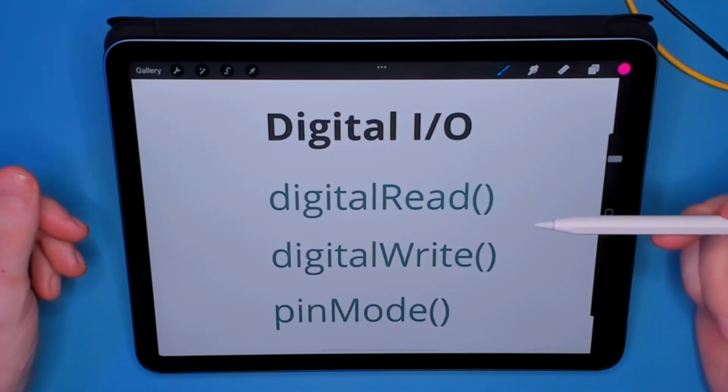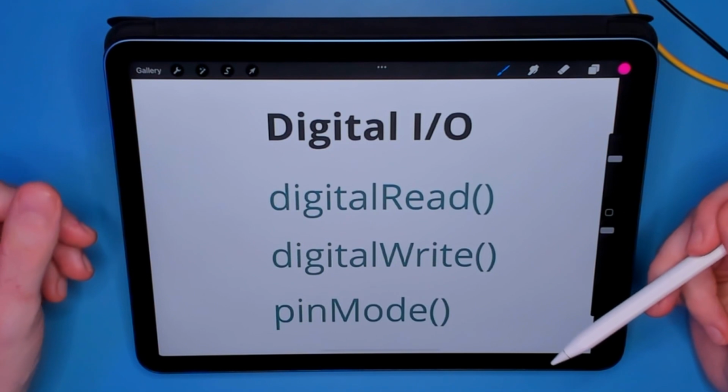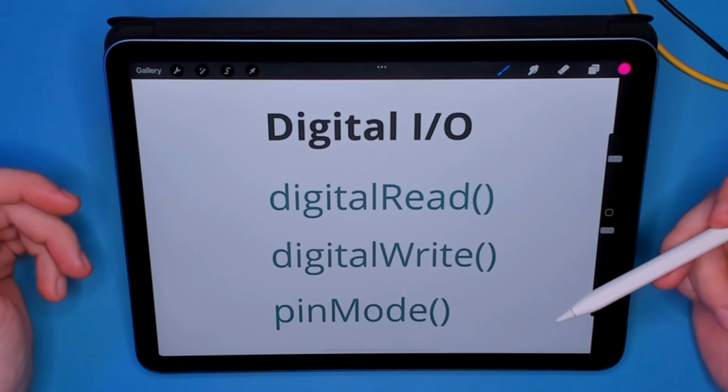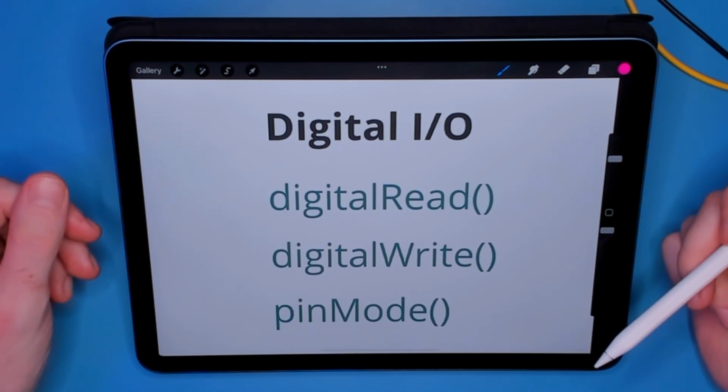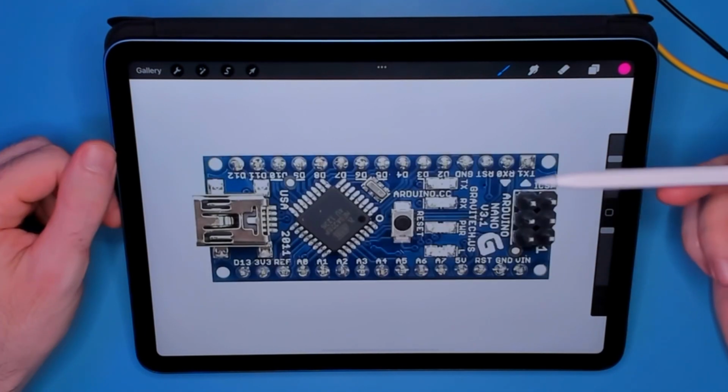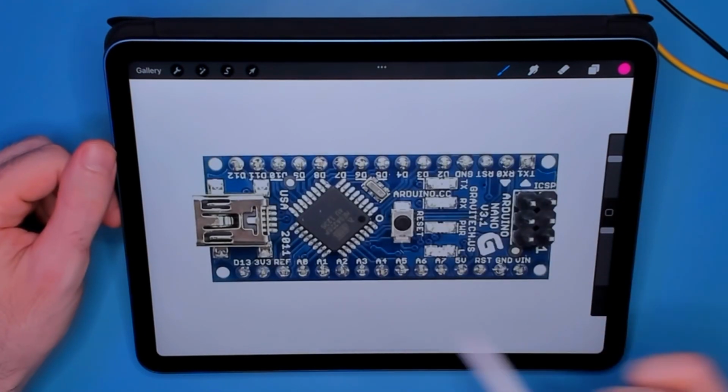Before wiring things up though, we'll need to figure out which microcontroller pins should be hooked up to the DAC. To control the DAC, we're going to need something a bit more advanced than Arduino's digitalWrite. This function, along with digitalRead and pinMode, were lifted from an earlier project called Wiring, and were designed to simplify things by mapping out a set of virtual pin numbers, specifically the ones that you can see printed on the Arduino circuit board. This way, programs written for different kinds of microcontrollers can just use the same virtual pin numbers, and the low-level details will get worked out by the software library.